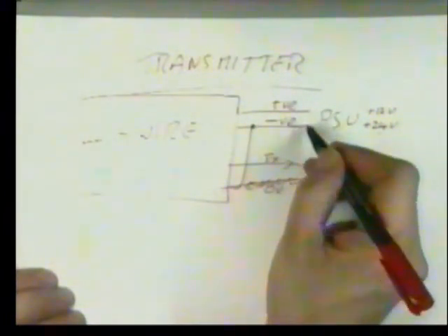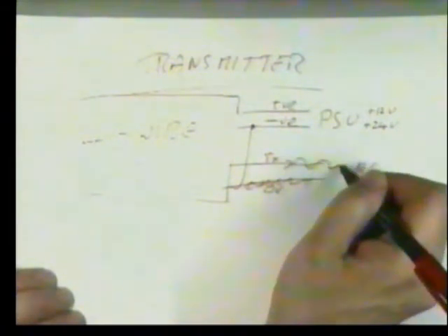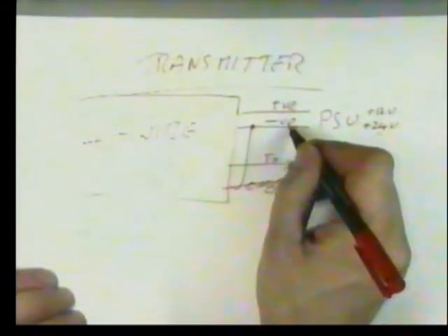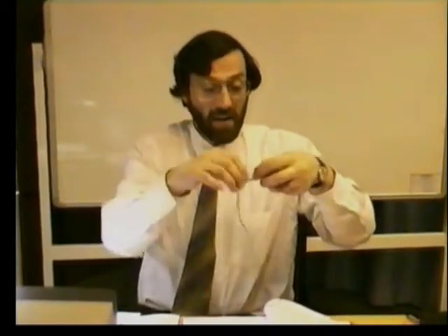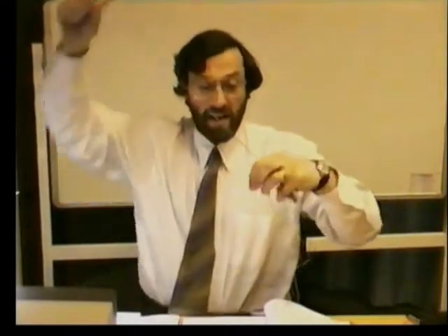So we have our power supply and we have our transmitted signal, whatever it is, relative to the negative power supply. And by combining together our return and our 0-volt signal into one, we can just twist those together. That now becomes a single wire, a 0-volt for our power and a return signal for our transmission. We have a 3-wire transmitter.